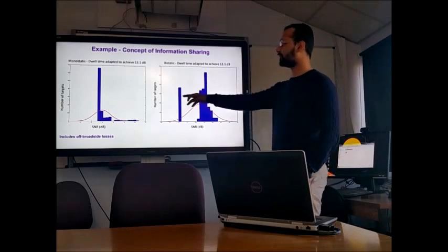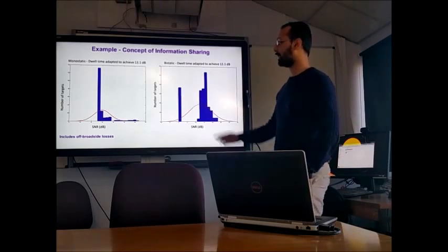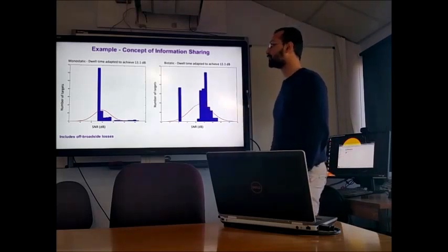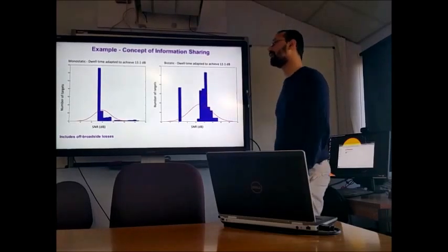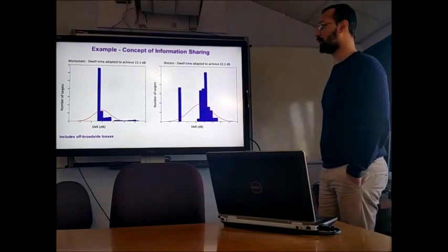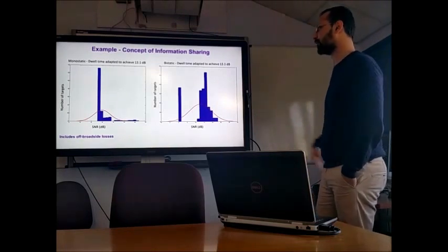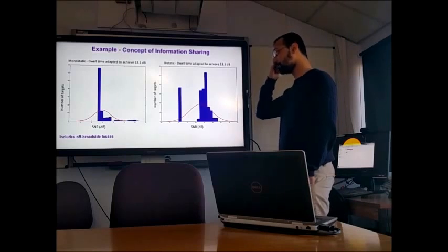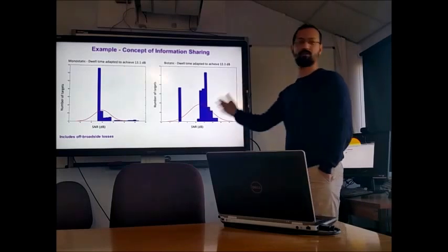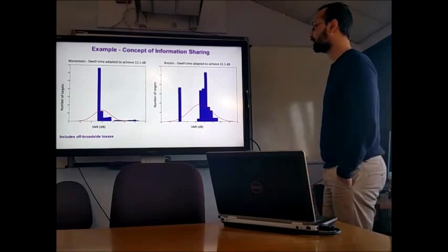What we see on the left side, which shows the distribution of SNR for the targets within the simulation, is that most of the targets end up in the 13 dB bin, which is what we want. And some of them do have greater than 13 dB SNR, but we have no control over that because the SNR is just higher since the targets are closer in.